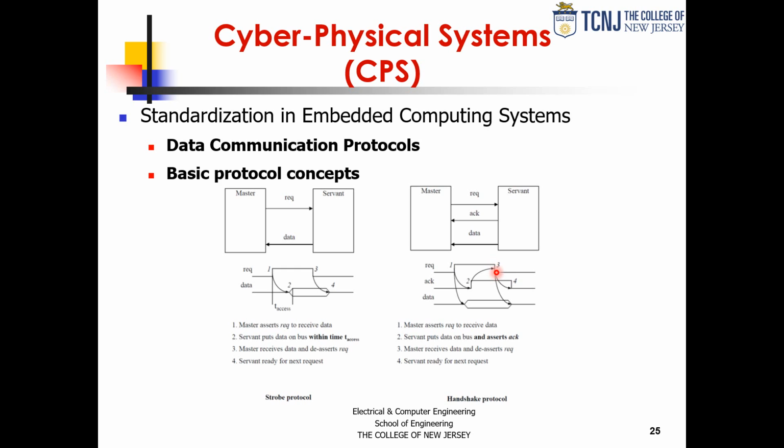That is a signal for the slave to say, well, the master got it because it's deasserting the request line. And then at that point, the slave deasserts the acknowledge, so a not acknowledge or a NAC. That concept of ACK and NAC, that is used in I2C, for example. And at that point, it can basically free the bus.